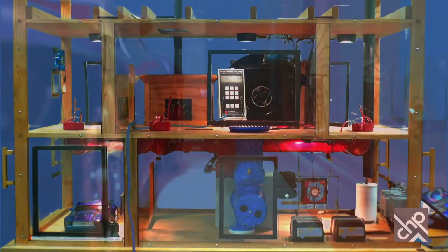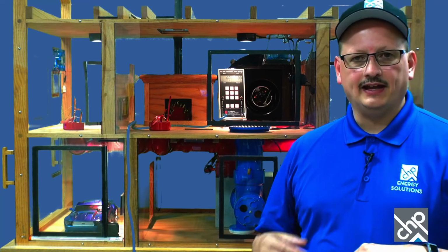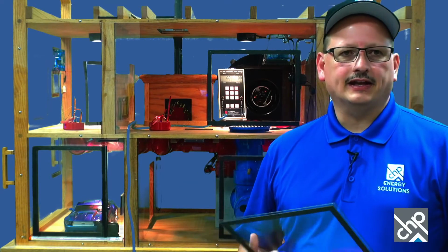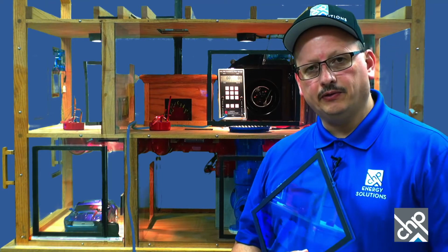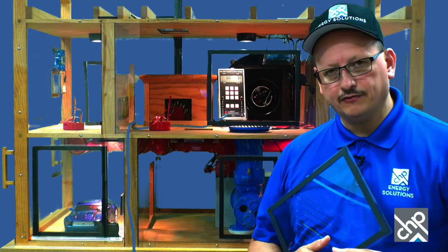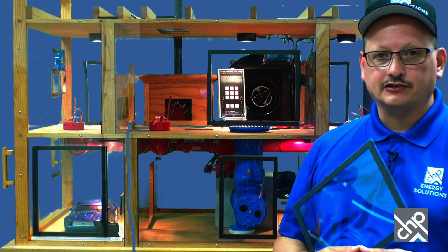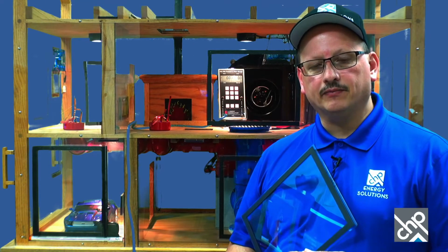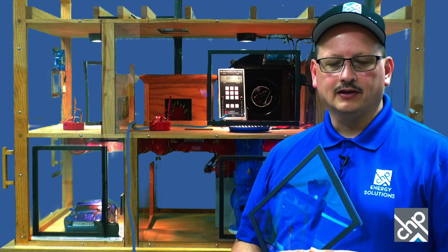And so what I want to do now is talk about exhaust fans and door closure and duct leakage and those types of things. The first thing is, if you've got exhaust fans, they're sucking air out, and we use those a lot in weatherization and home performance. You have dryers, bathroom fans, kitchen fans, and a lot of times that gets put in as exhaust-only systems. So if those are sucking air out, that means it's got to have air come in from somewhere else. If you've got 100 CFM going out, there's got to be 100 CFM coming in.